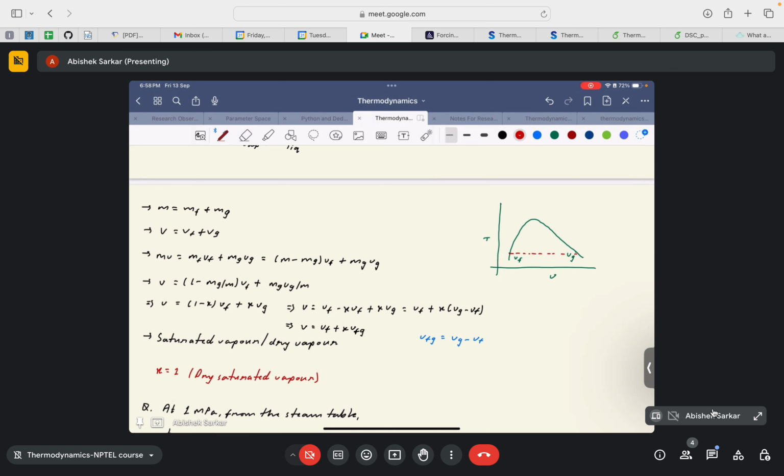Just try to go upwards in the diagram, then you'll get a hint. CP, yeah, critical point, exactly. So if we go up the diagram, say you are dealing with steam at this particular saturation temperature or pressure, you can see the difference between the specific volume of the gas and the fluid has reduced, and you'll see that this trend continues up to the critical point.